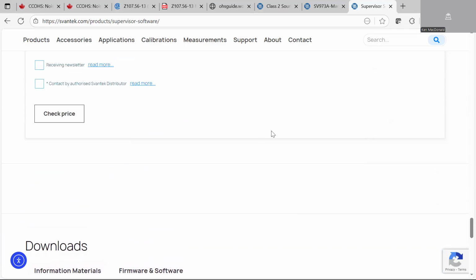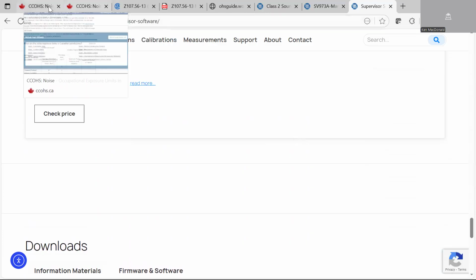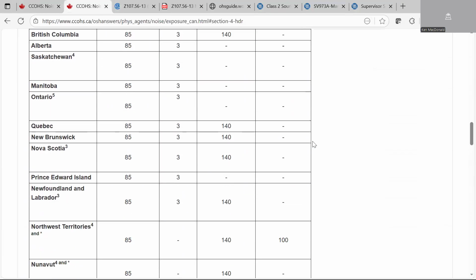Especially with the software and, for example, in the dosimeter, a lot of these settings are programmed. A lot of these are based on ACGIH values. So in the software for the dosimeter, especially, there's a pull down menu. You can actually choose ACGIH and it automatically fills these in for you. So it makes it a bit easier, but it's good to know where these come from.